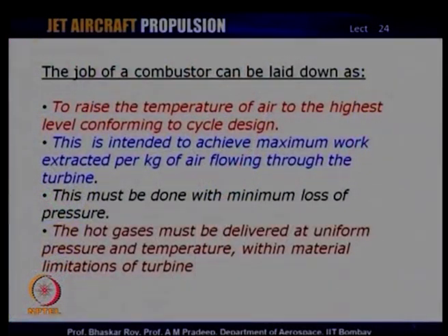We can indeed list them: to raise the temperature of air to the highest level conforming to cycle design. Now, this is as per the turbine inlet condition as specified in the cycle design. The turbine inlet condition is indeed decided by the ability of the turbine to withstand high temperature, which is decided by the state of the art of material science and metallurgy, and the cooling technology often employed in turbine design.